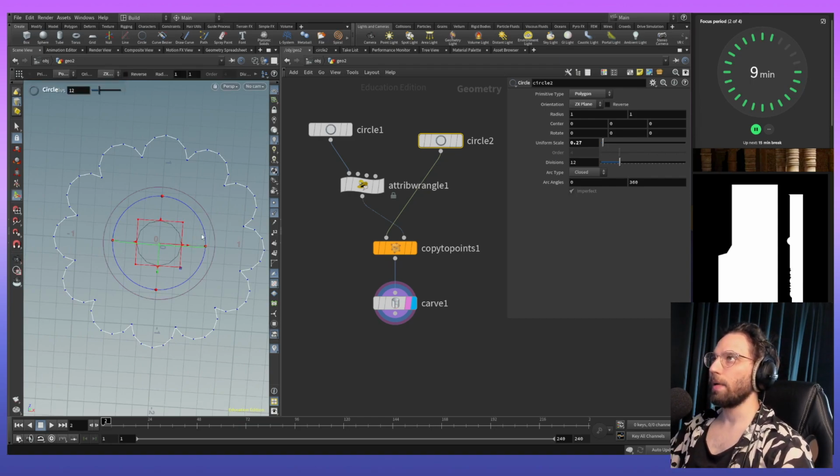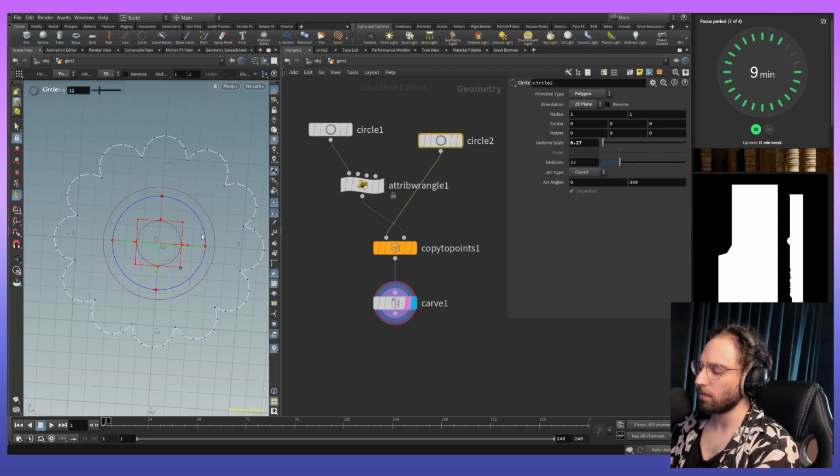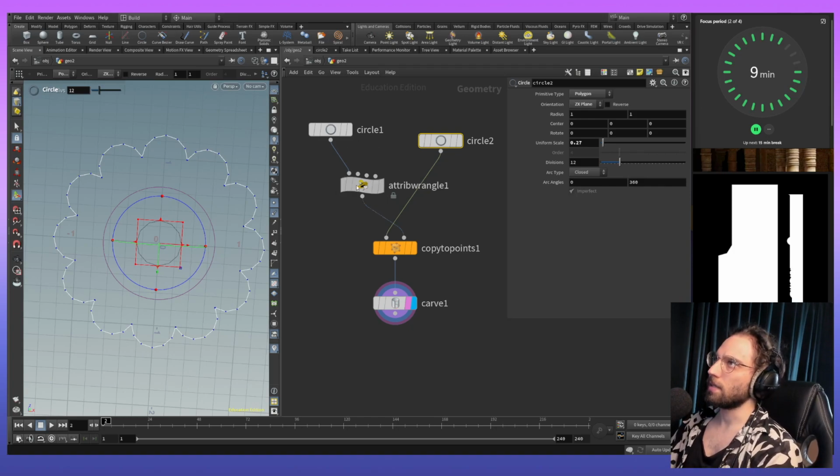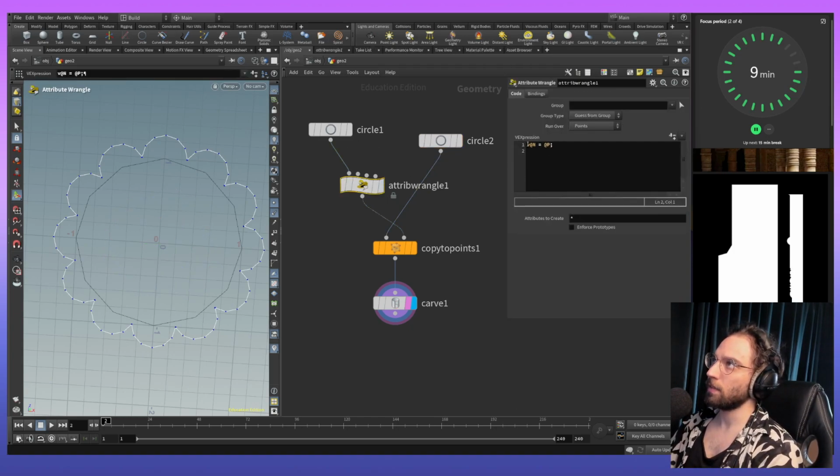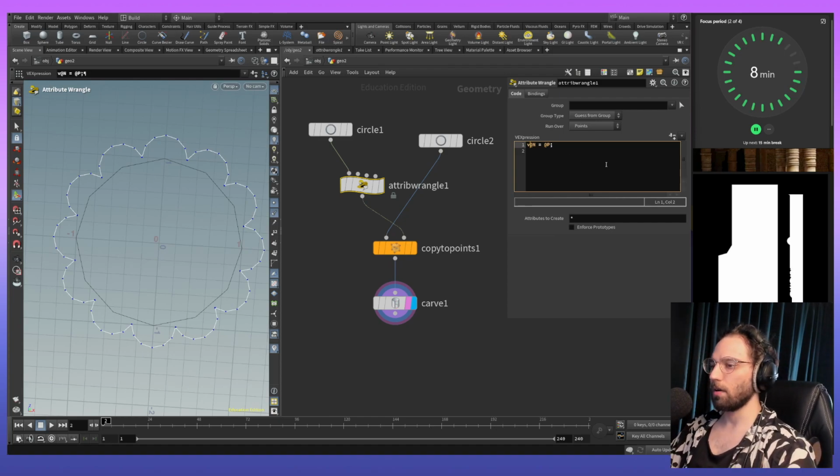Okay, so now we get it a little bit better, right? I have a better understanding of it, and the way to write the code is just for review for me: v@n equals @P, and the @ is only something you could add if there was an attribute that is called this way, because before my mistake was that I added @vn, and that is just not correct. Okay, we will save that and continue learning.